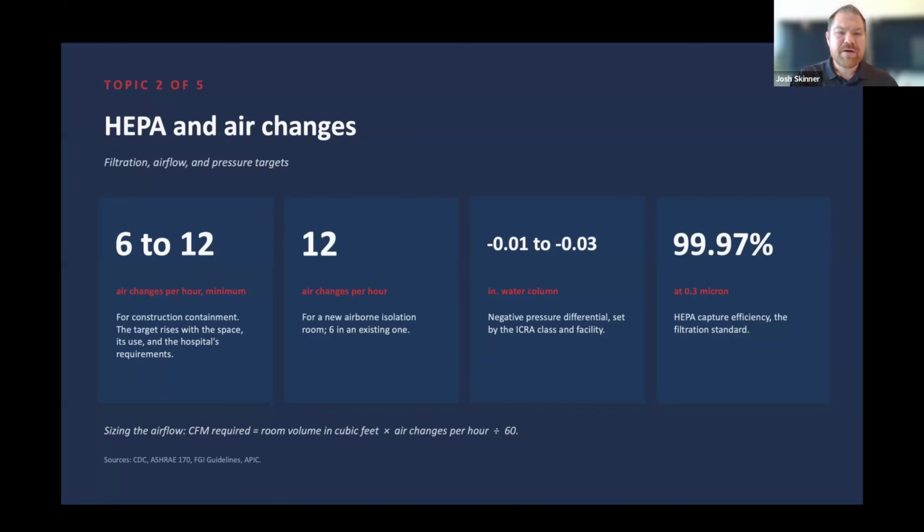Just go in there, go through a regular schedule. Pre-filters changed at least, in most cases, weekly, depending on class 5 or class 4 containment, and HEPA filters changed on a regular schedule. So then you're never in a place where you're worried, is this overclogged? Yeah, the light will come on in theory, but machines don't always get treated the greatest, they get beat up, lights get ignored.